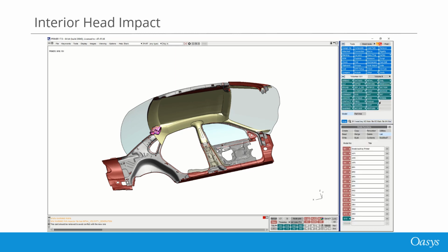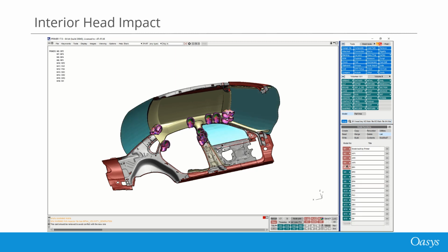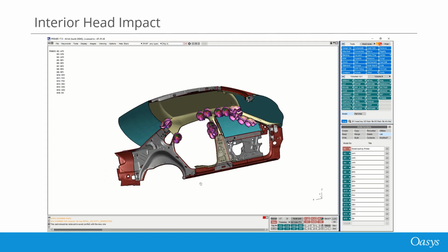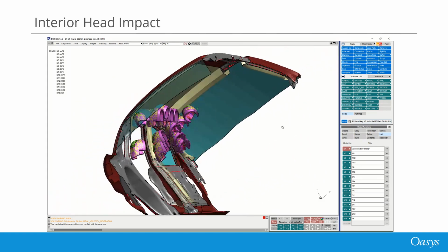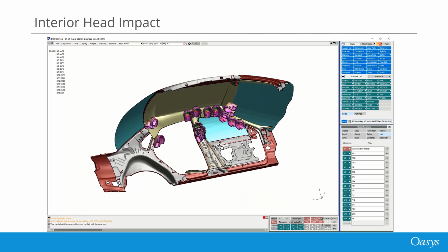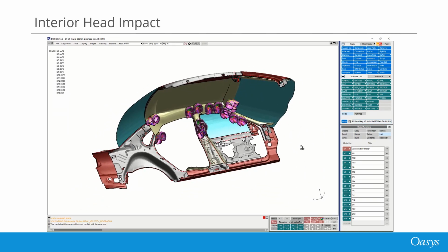So now it's finished. It's built all the models. You can see all these models are in Primer here. It's also written these out to disk. So there you go. All these models being created, positioned, depenetrated. And Primer doesn't create copies of the impactor here. It'll create the include transform information required to move the impactor from its standard position to the final position as calculated by Primer.